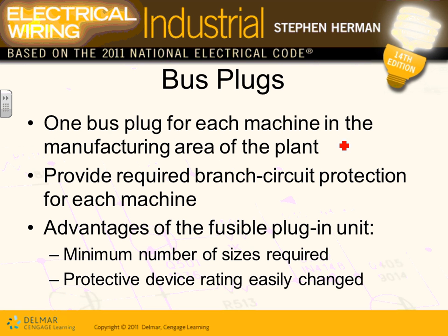Then what they have is something called a plug for every machine, guys. Every machine on the manufacturing floor will have a plug. Derek, my friend, you're looking at it right here. It says ML here. Plug. A plug is basically a fuse disconnect, and you plug it in and you tighten it, and you take an SO cord from it and you feed your machine.